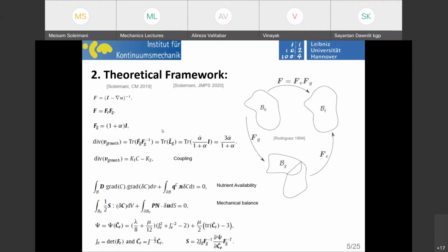On this slide, this free energy, is this per unit reference volume? Is it per unit volume, or is it just free energy? Yeah, it's free energy. This psi, you mean, right? Yes, this psi basically is the Helmholtz free energy. If we were talking about Hooke's law, then the Helmholtz free energy is something similar to the potential energy in a spring. So 1/2 kx squared, roughly speaking. But here, if you are in the hyperelastic framework, then your free energy is a function of the invariants of C, and that C is related to this elastic part of the deformation gradient. So the trace and the determinant, and of course the cofactor that here is absent, but this is the overall concept of that.